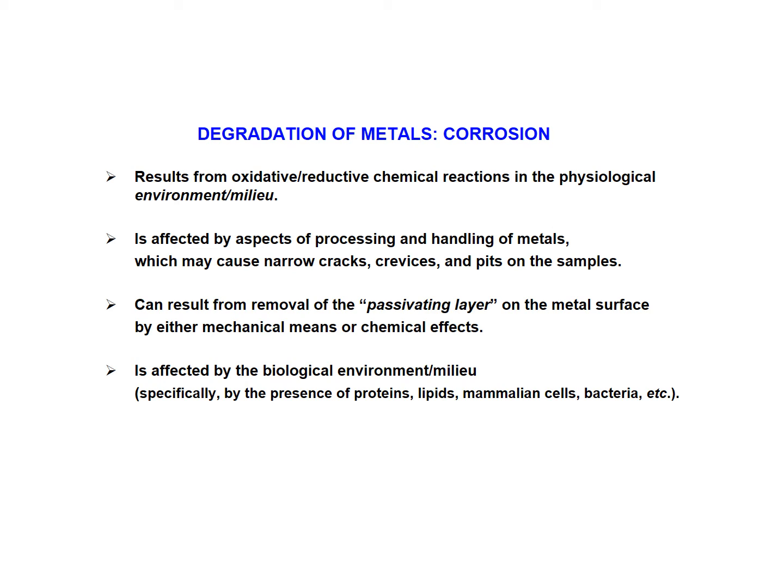Degradation of metals also is affected by the biological environment. Proteins, lipids, cells, bacteria, and all the chemical compounds that the activated cells and bacteria may release can be attached on the surfaces of metal implants, and they may start the process of corrosion.